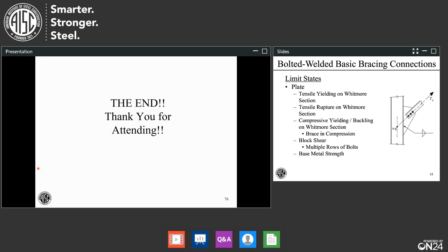Guide 29. One of the things about chevron type connections is that they are not statically indeterminate like the connections we were just dealing with, our corner connections. So you're going to rely on lots of section cuts and free body diagrams to determine forces and loads there. And there's going to be lots of judgment.